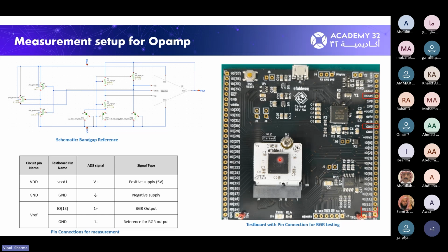And similarly, you want to do measurements on wafers which have been processed at different times inside a foundry containing this design. That's where you will see if there is any effect happening on your design due to the process, and if the bandgap reference circuit is giving a constant voltage across the process variations in different die samples. So that requires a very sophisticated setup.